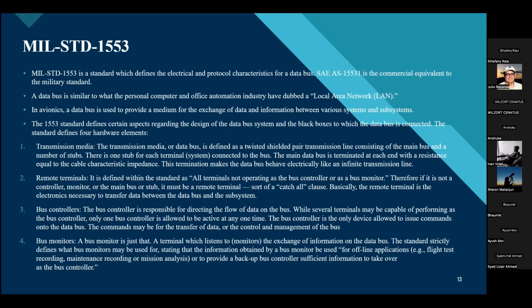And the messages in this avionics databus are up to 32 16-bit words. It is a two-sided bus, and transmission speed is 1 megabit per second, and it is well protected from disturbance, so the data can move smoothly in the system.